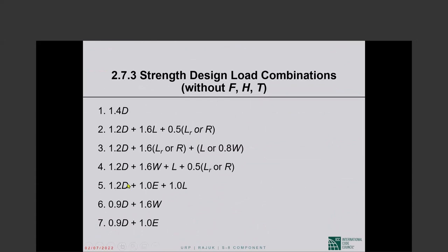Two of the load combinations have earthquake effect E in them. I call this the additive seismic load combination. The gravity causes negative bending moment at a support section. Earthquake also causes negative bending moment. If we want to figure out the largest negative bending moment at that section, we will use that load combination. Gravity adds to the effects of earthquakes.